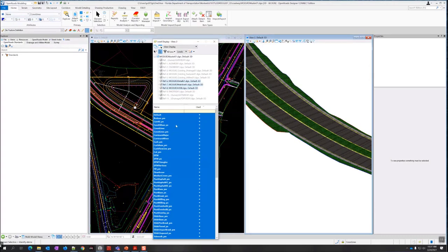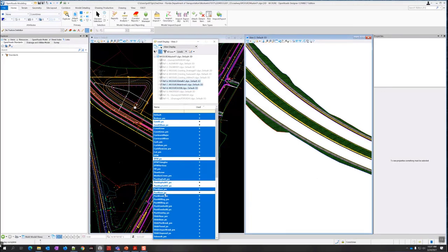And so we're on step 6, exercise 5.6, and it outlines everything that needs to get turned off. Let me see if there's any filters that'll help me out here. I don't think we have one specifically for meshes. So if I just sort by use, I can see it here and just look for anything that's underscore PX and turn those off. So you can see the meshes going away here.